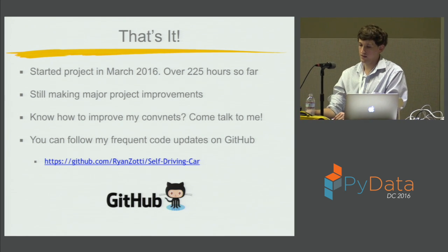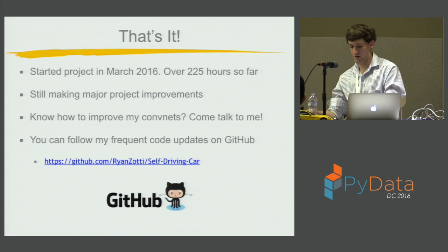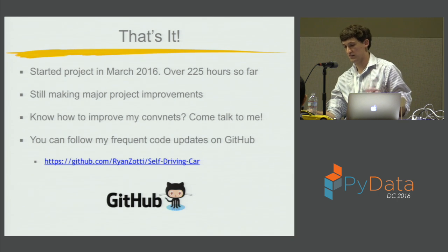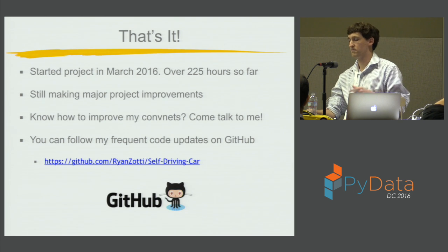But yeah, that's actually probably one of the most complex pieces of my project: how did I actually collect the data? So I had just 3 commands: forward, left, right. I did that from my keyboard on my laptop. I set up a Tornado Python web server on my Raspberry Pi. It's really lightweight. It's very fast. It's asynchronous, and it would basically listen for these commands, left, forward, or right, and then pass those on to the motor, save those commands to a text file, and then simultaneously save the streaming video to an MOV file.